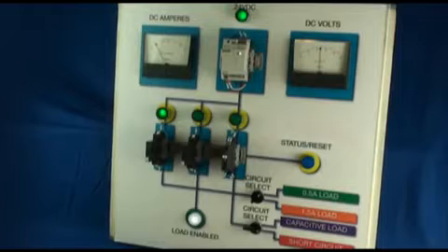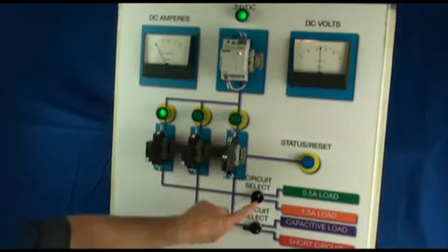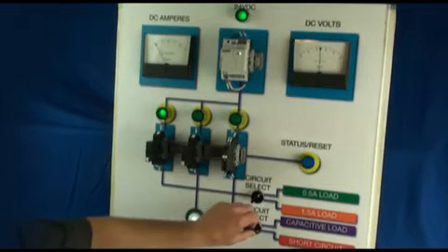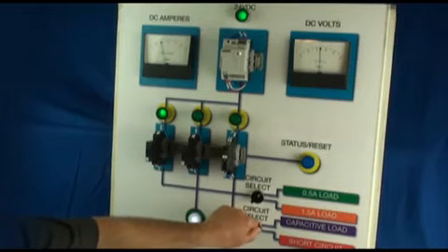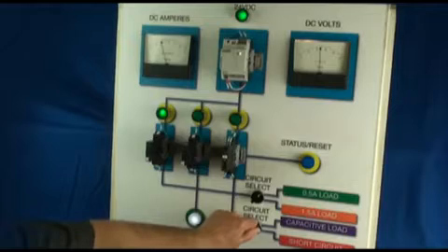The first condition will be with circuit breaker 1. We have it set at the 1/2 amp load setting, and we will apply the capacitive load. You'll notice the breaker does not trip, but the amperage does ramp up to close to 1 amp.